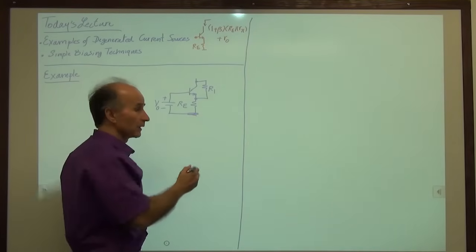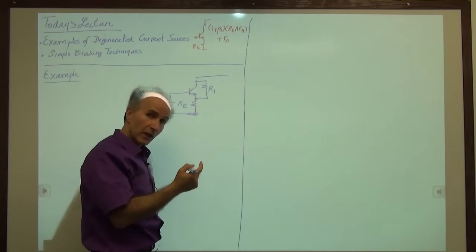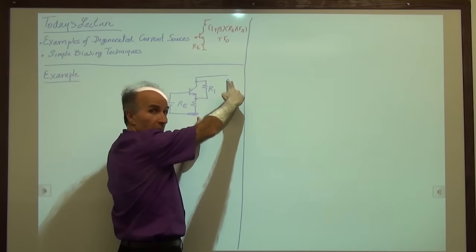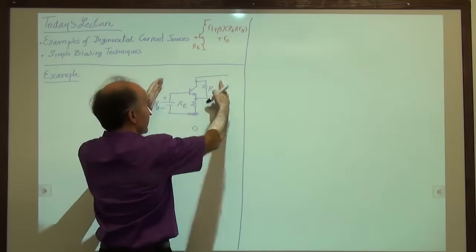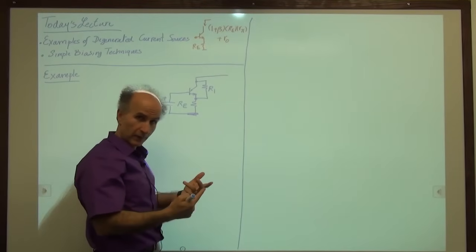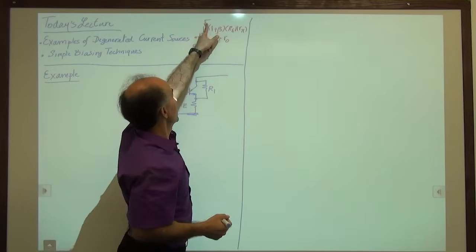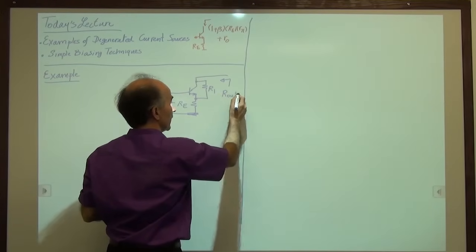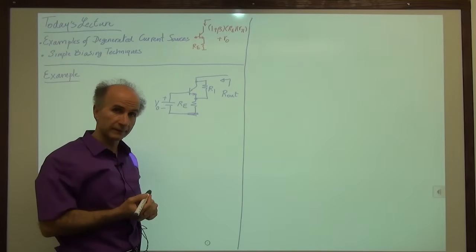And now I would like to find the output impedance of this device. So if you remember, the output impedance is really measured between this point and this point, because the way we would do it is kill all the independent sources, then place this in a box, apply a voltage source between these two terminals and an AC voltage source, and measure the resulting current. But as an abbreviation, we usually just put an arrow and we say Rout. And that's just a simple notation for what that would entail.